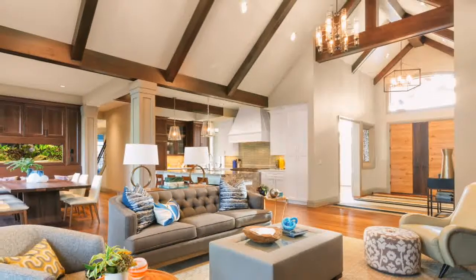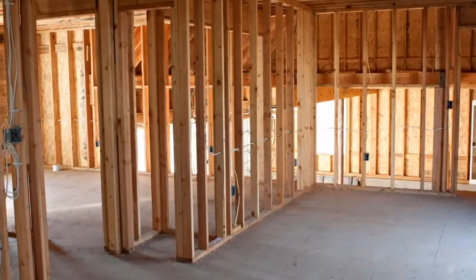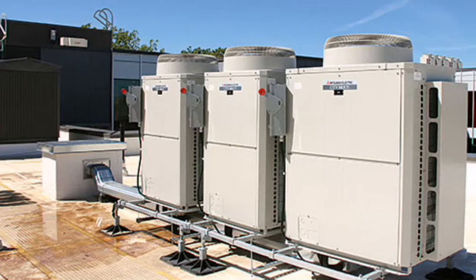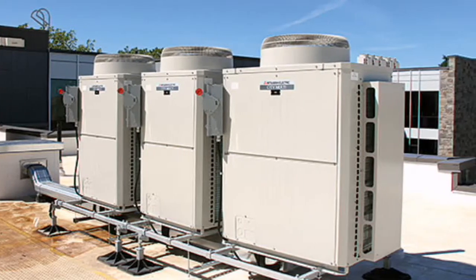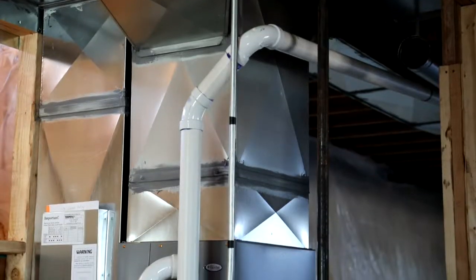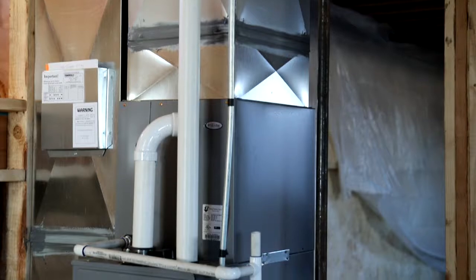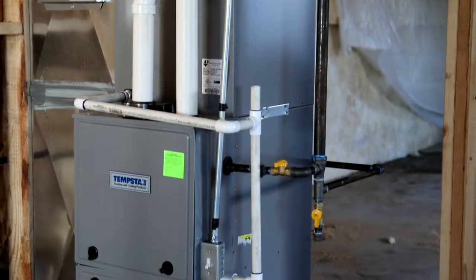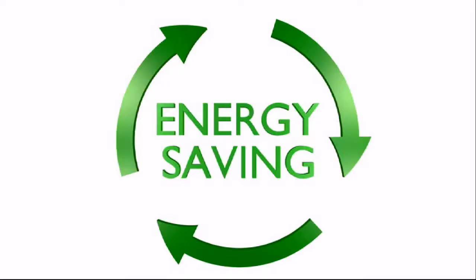In conclusion, zoning can be retrofitted to any building or home, although the installation at the time of construction is best. Systems which can simultaneously heat and cool are the most expensive and complicated, but simple zoning systems using existing HVAC equipment are inexpensive and easy to install. Heating only and cooling only systems are available, but most systems allow for both. Zoning does save energy, which will pay for the equipment over time.